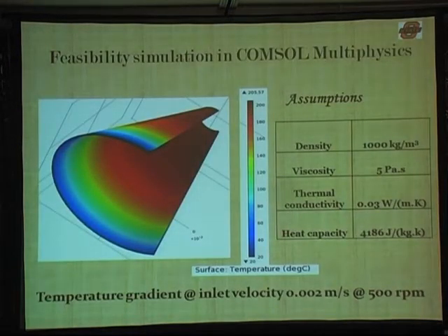So we went through a series of CFD designs and we tested this. I'll show you just a couple of these, except for the color, the pictures aren't that exciting. We took an angular design primarily so that we could adjust spacing by rotating the core and the shell relative to each other, rather than having to build several different shells or cores and then changing parts repeatedly. We can just move a lever and we can adjust the spacing for a design variable.